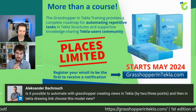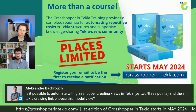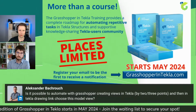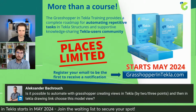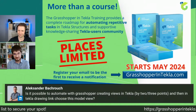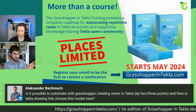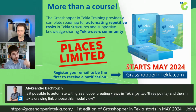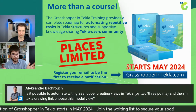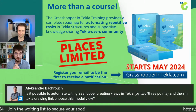Correct. Thanks. Alexander asks, is it possible to automate with Grasshopper creating a view in Tekla by 2-3 points, and then in Tekla Drawing Link choose this model view? One of the samples which we have not covered was about the model views. That's on the GA drawing, where you want to get this specific model view. And there is also a component that will list all of the predefined model views. So it is possible. And that's all for now.